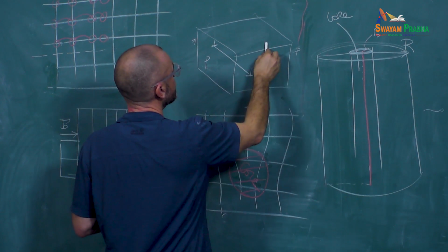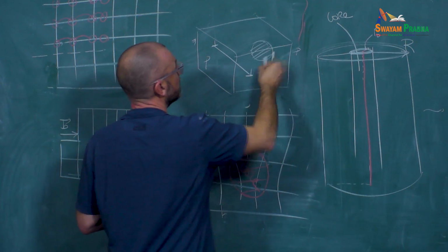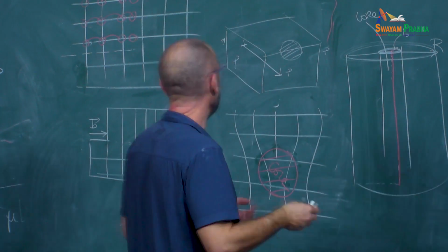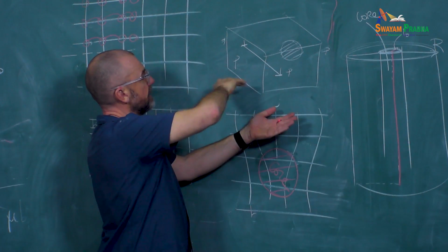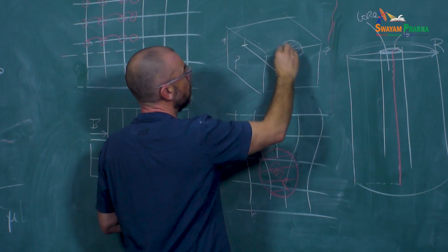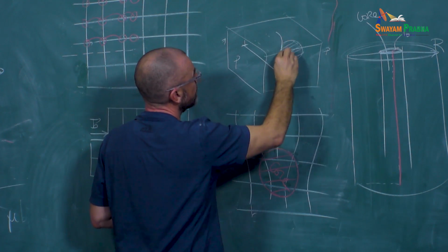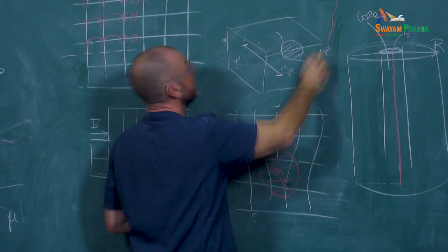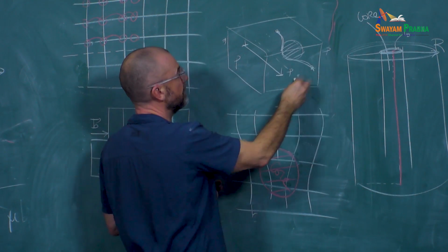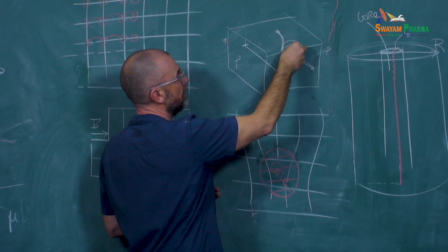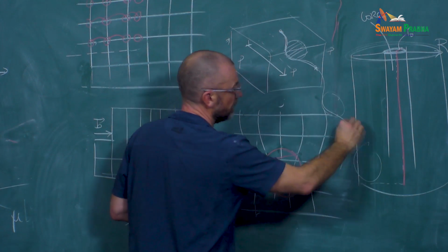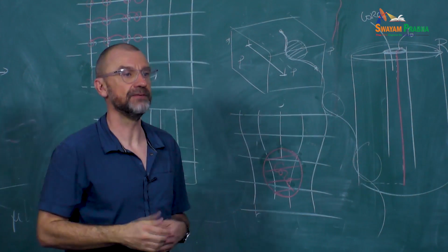And then in front of the dislocation, somewhere here, I put a precipitate, for example, or an irradiation defect, a loop. I don't want to go into that today, but imagine that I shear the system. The edge dislocation will move, will come in contact, and then it's going to do something like this. This part being connected to that part, but then it's going to bow out in between. Because now with the periodic boundary conditions, what you have is not one precipitate; you have one here, but then you have periodic images of the same defect, and so the dislocation will bow out between the defects.